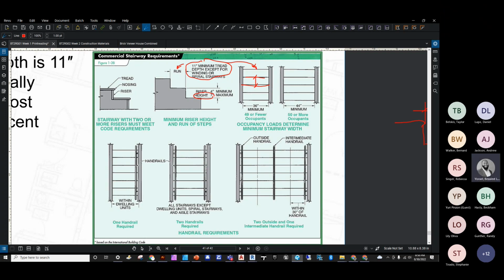Hey, Lewis, what you got? So just to understand and verify what you were saying here. When you're designing a stairway, you can't go over 12 feet without a landing. So it has to be under 12 feet. If it's over 12 feet, you have to have a landing area, and then you can continue on. Say in commercial use, where it's a long vertical stairwell between floors. Correct.